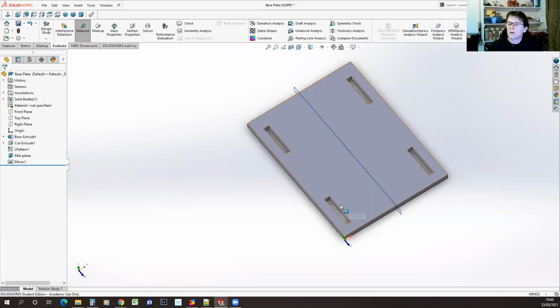And now when I go and measure, it should. Oh, my measure toolbar is appearing on my other screen, so you won't have seen it. This little toolbar pops up. If you click away when you're using the measure tool and click on something else, then when you come back in, you're not always in measure mode. If you don't get a green highlight when you click on something like that, you need to just select the toolbar again.